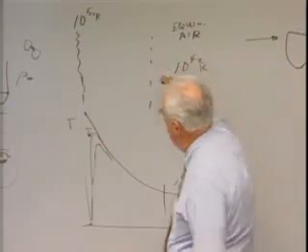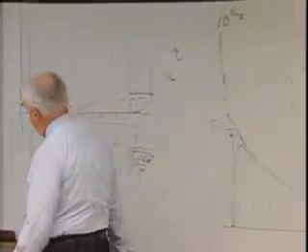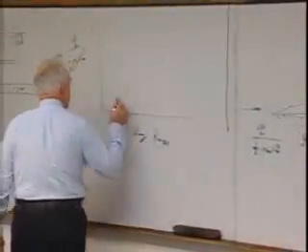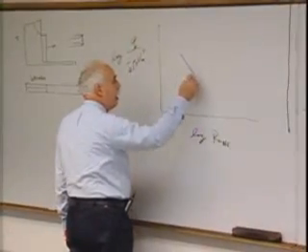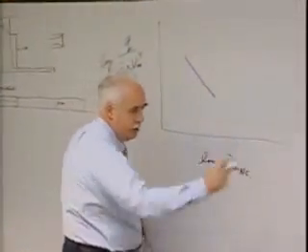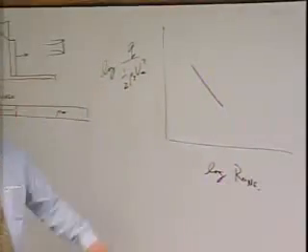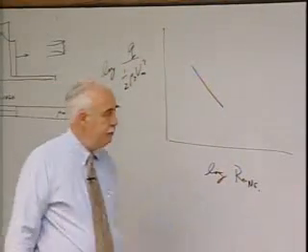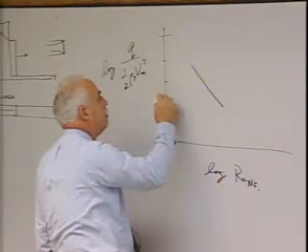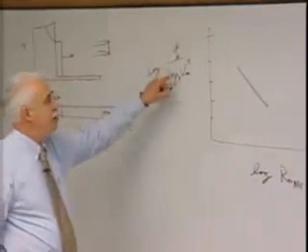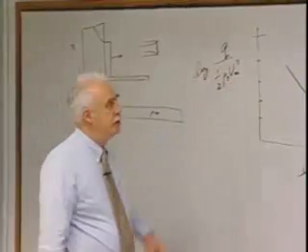Okay. If I look at either wind tunnel data or flight data, in the region of prime concern, I've got that -1/2 slope from that square root Reynolds number. I also have a bound up here, that my heat transfer cannot exceed the energy flux.